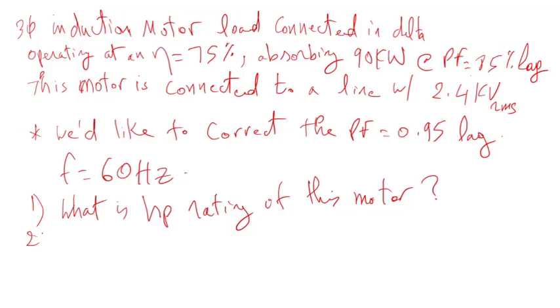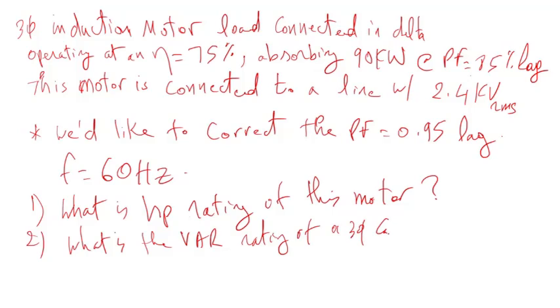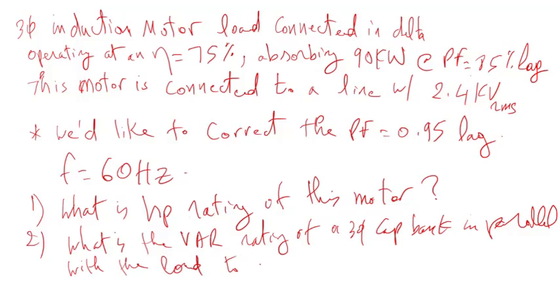And 2, what is the VAR, volt-amp reactive, rating of a three-phase cap bank, or capacitor bank, connected in parallel with the load to correct the power factor to 95% lagging.